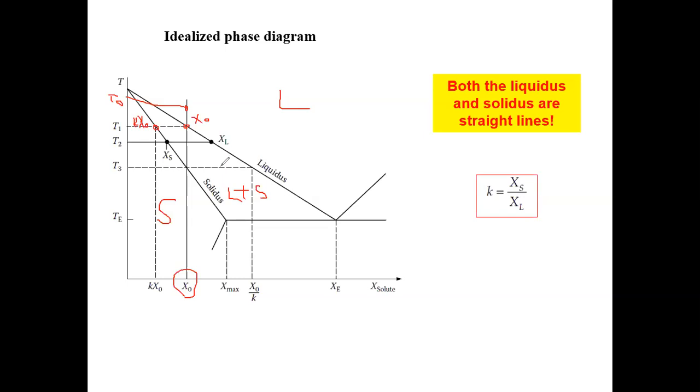Okay, so now let's cool the system. Before we cool the system, let me ask you. Let's consider we have a bar of alloy, and the heat is taken away from this direction. This is my heat flux. At T1, for example, I know that I'm going to convert a small amount of liquid into solid. So my question for you is: if I keep the system at this temperature, a little bit lower than T1, will the solid phase grow further?